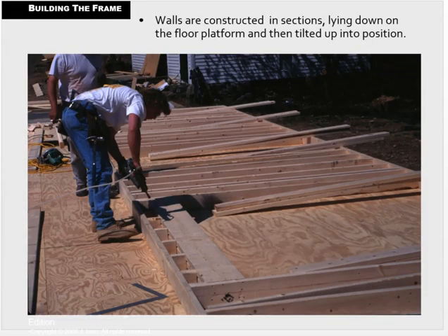And here it is. This is what it commonly looks like. So again, our bottom sill plate laid out. At the same time, our top sill plate is laid out. So that's the carpenters with tape measures and squares, putting all the information on both. Separate them, laying in the studs, putting in the window headers. These are called cripples above the window. This is the top sill plate. As it goes up, it will stand high, stand tall.